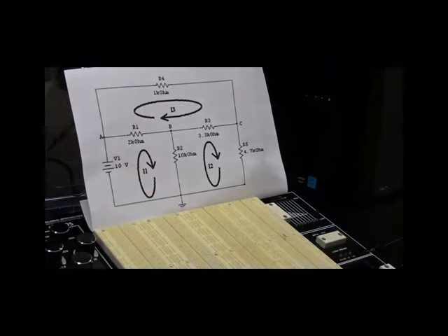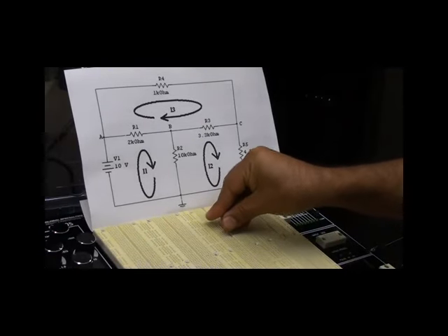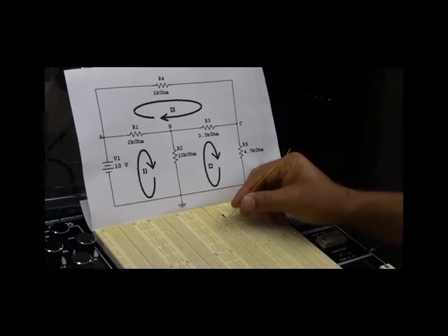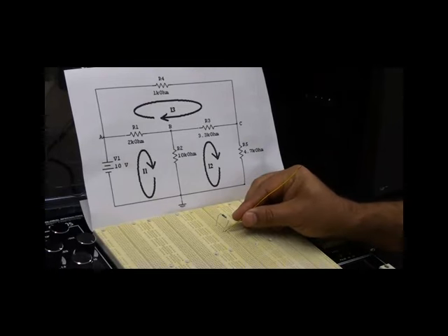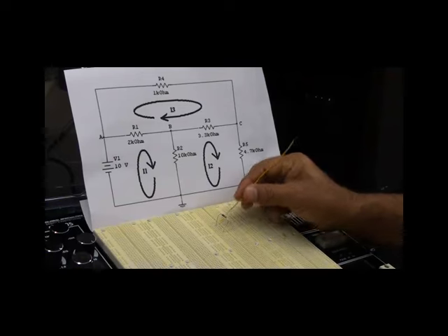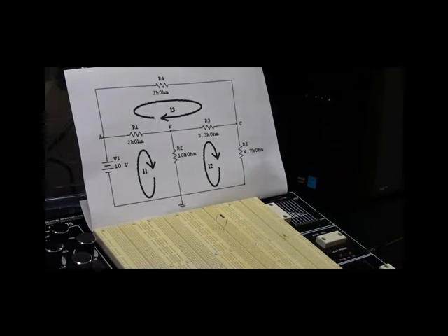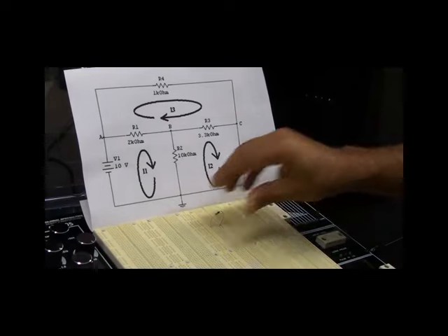It's a horizontal resistor, so I'll just put it on the breadboard in a horizontal way. Of course, I have to pick 2 different holes which are not connected. I know the holes in this column are connected together, but holes in this column are not connected to the holes in the other column. So both pins of the resistor are not connected together. Make sure you do that right. If you do it like this, this is wrong.